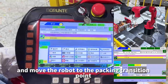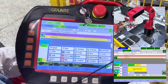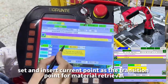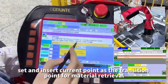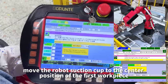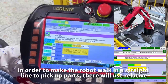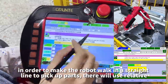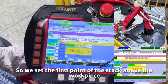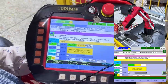And move the robot to the packing transition point. Set and insert the current point as the transition point. For material retrieval, move the robot suction cup to the center position of the first workpiece. In order to make the robot walk in a straight line to pick up parts, we will use relative. So we set the first point of the stack above the workpiece, and use the relative to move in a straight line to pick it up.